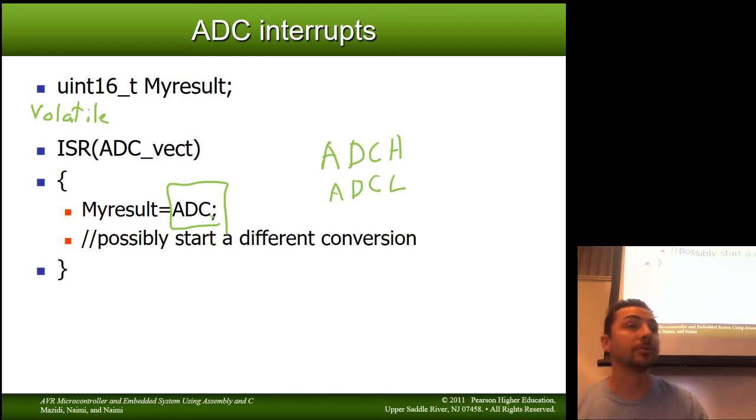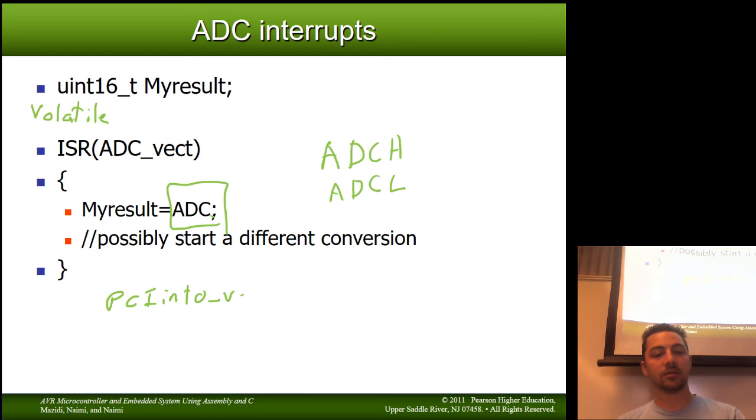So in the lab, in phase 3 says, hey, when you press the button, start an ADC conversion. So you might have a pin change interrupt vector that just says, all right, in the ADCSRA, turn on the start conversion bit, AD start conversion.